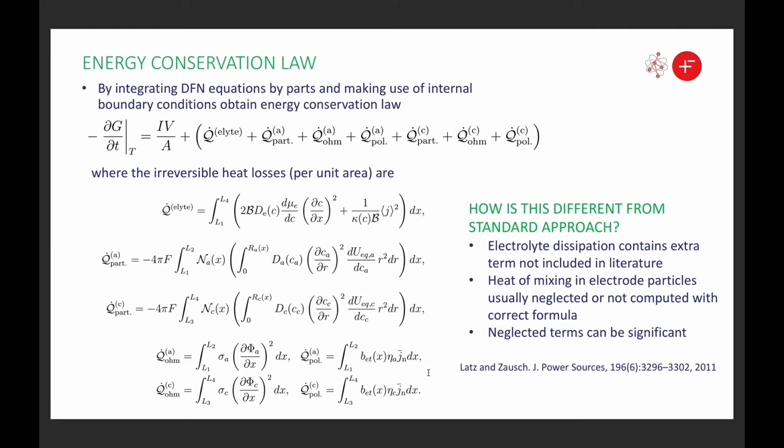And if you go and compare that to what people write down for the irreversible energy losses for the Doyle-Fuller-Newman model, you see that these bottom four terms are actually identical to what people will write down.